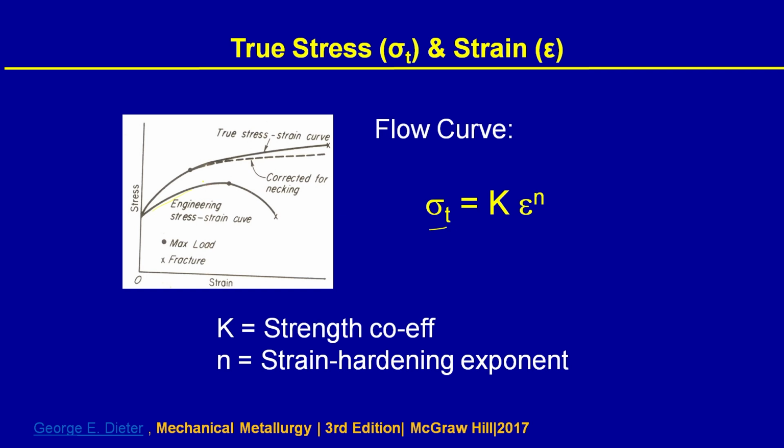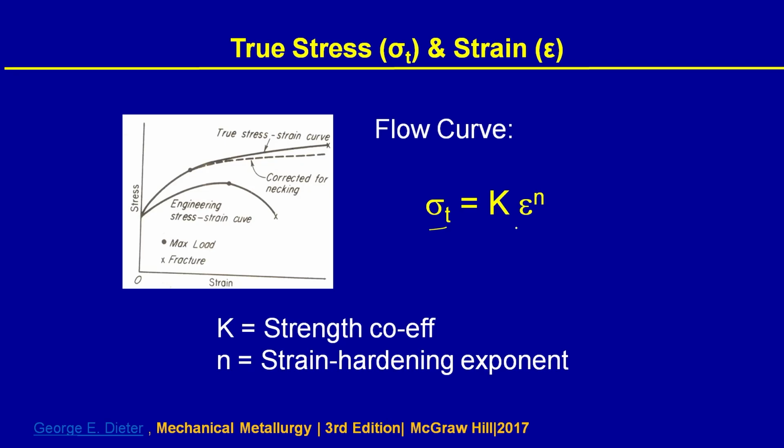That is why if you take a piece of metal or steel and actually hammer it, after that if you measure its strength, it will be much stronger. By hammering, you are introducing a lot of defects, and these defects will increase the strength of the material. That is what is called strain hardening, and n determines that behavior. n tells you the strain hardening coefficient, how it is going to change as the material is deforming. So, these two parameters are fundamental material properties. You should know them very carefully if you want to design new material.